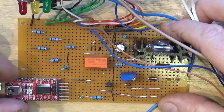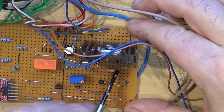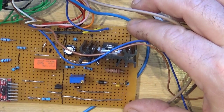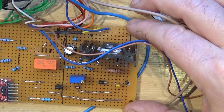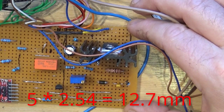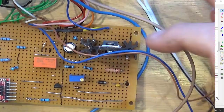The only other resistor is this one, the power resistor for the current sense, which is 5 holes along, which is 5 times 2.54 millimeters, because I can't work it out in my head. So let us start assigning footprints to some of the resistors on our PCB.